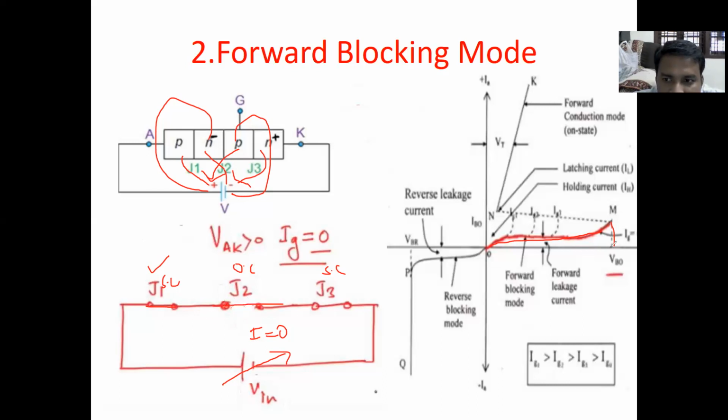That is why you can see the voltage coming down in this picture. Because of breakover, it is coming to this position, and short circuit takes place. A huge amount of current will be flowing in that path. So that is the reason we don't operate in breakover mode.